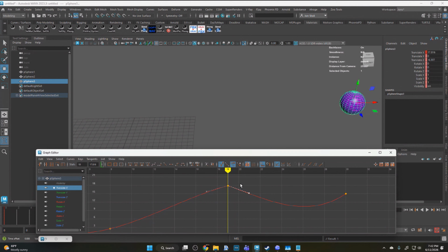What this program's doing is it's saying I'm going to move these curves along tangent based on these handles here, these little white handles. So it's always going to be tangent, but you can break those handles, and so you can break that tangent control. In the applications I've seen, the former, where there's a tangent, it calls a smooth node, and when you break it, it calls it a cusp node. I don't know about that. I've never heard that, but maybe that's right.